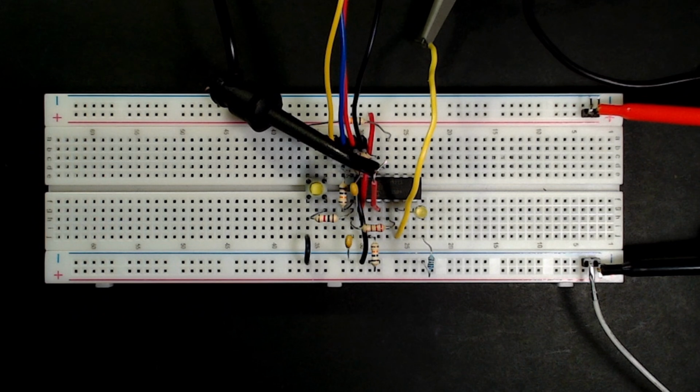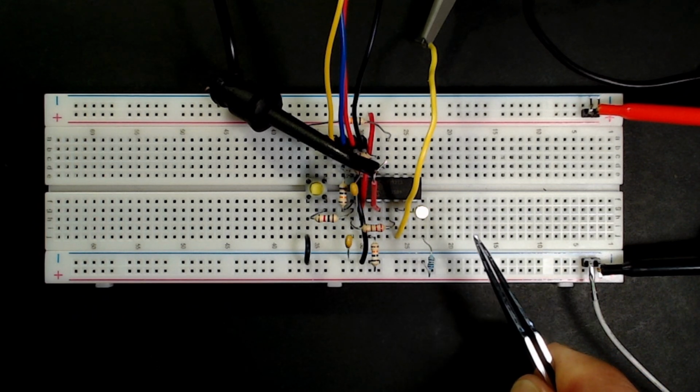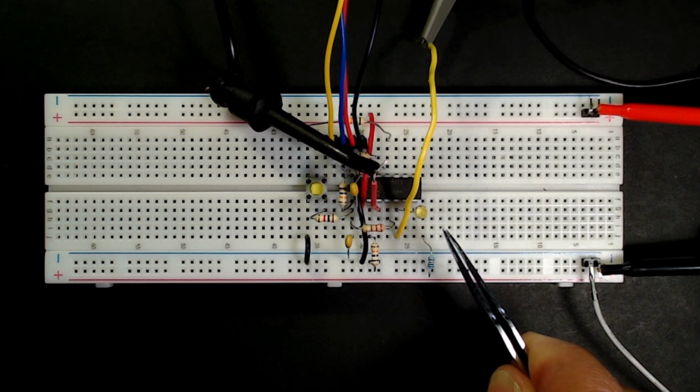250,000 kilohertz. Remember, we're looking at the instruction clock, not the system clock. And we already know that the system clock is 4 times the instruction clock. So 250,000 kilohertz times 4 is 1 megahertz. Well, it's running at 1 megahertz. And because of our wonderful timing algorithm, our LED is still blinking at 2 Hertz.